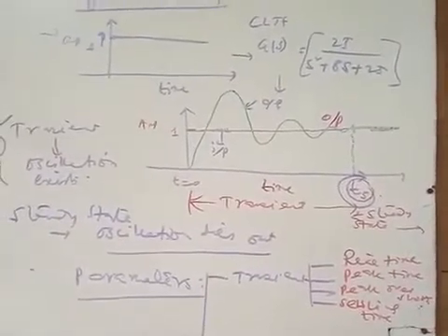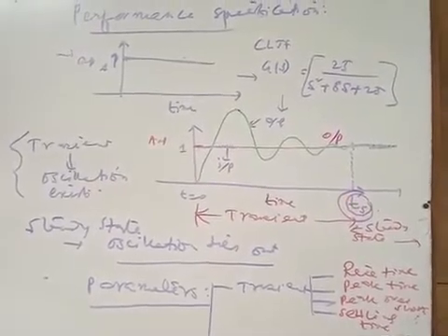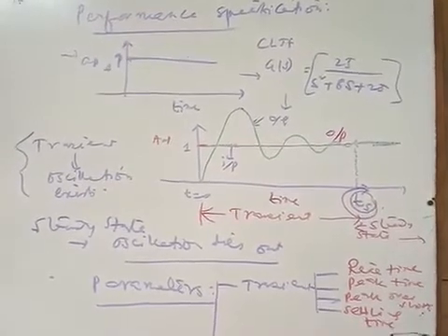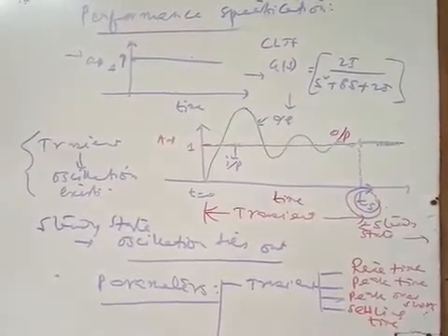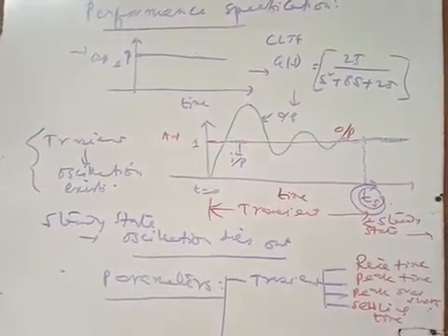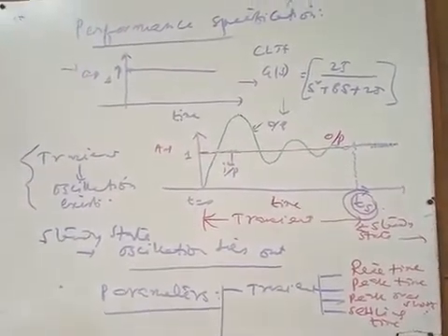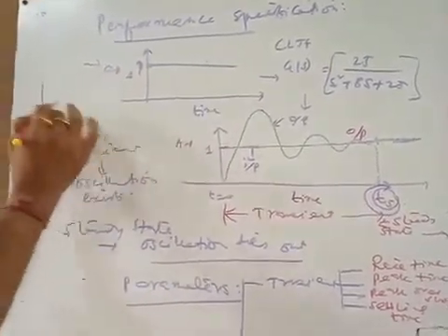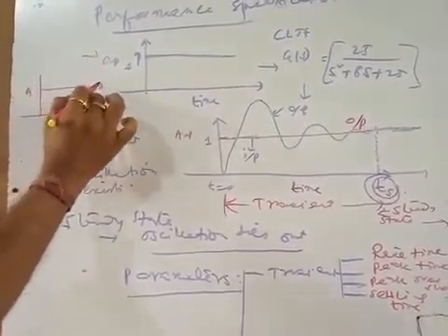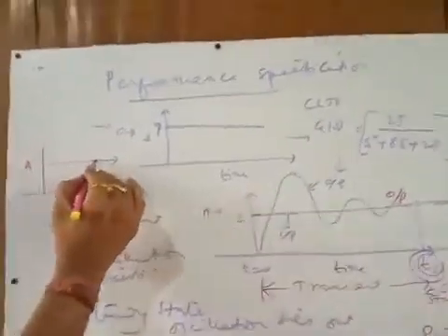So you see, this is the output response of a second order system corresponding to a step signal. In most cases in industry, the standard input signal used is the step, right? Why are impulse, ramp, and parabolic signals not normally used? These are the kinds of inputs available, as you have discussed earlier, but in most cases the standard test signal is the step, because of the characteristic of the step. This is your step signal. Its amplitude is constant throughout, so if any system is to follow it, it must reach a constant value after a certain interval of time.